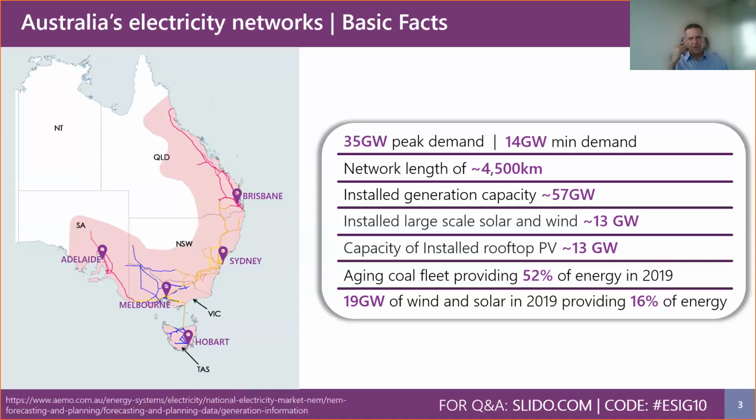It's an energy-only market with a 5-minute dispatch interval that is dispatched by AEMO according to demand forecasts. And AEMO also operates the national electricity market's total of 8 regulation and contingency frequency control and ancillary service markets. And these energy and FCAS markets are co-optimized in pre-dispatch by an economic dispatch engine that takes into consideration physical network constraints, demand, bids, and other economic factors.